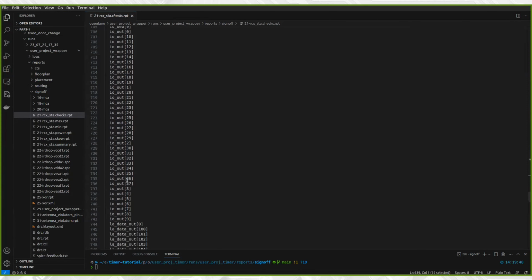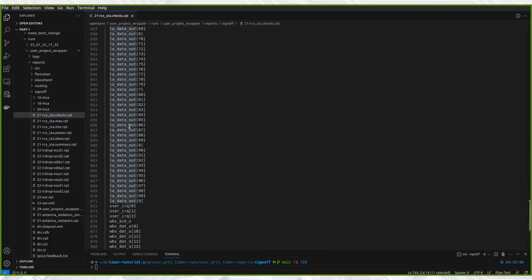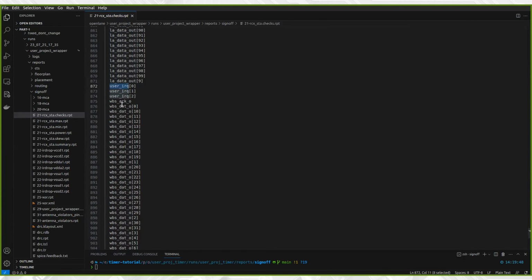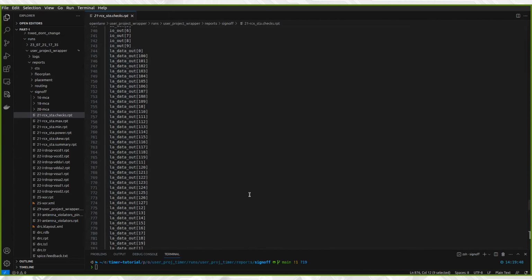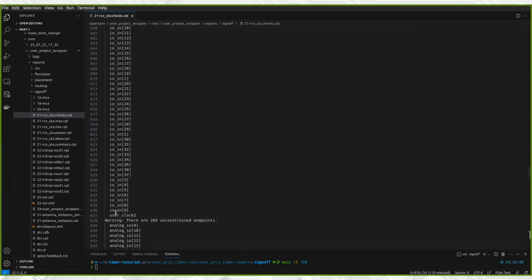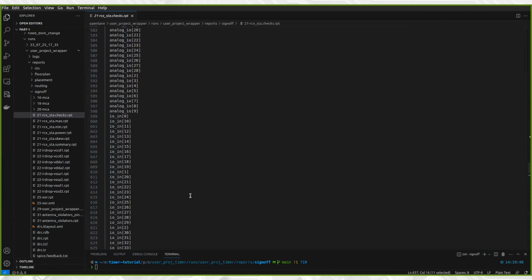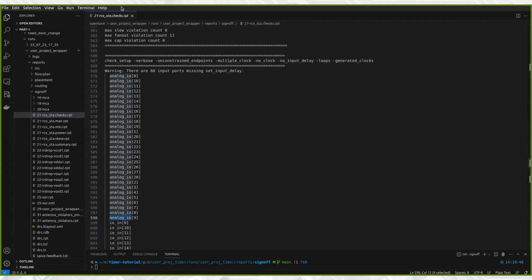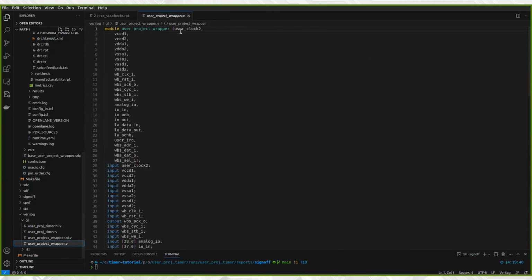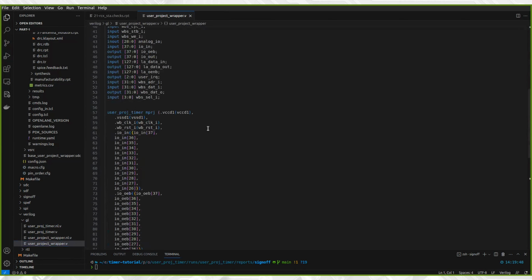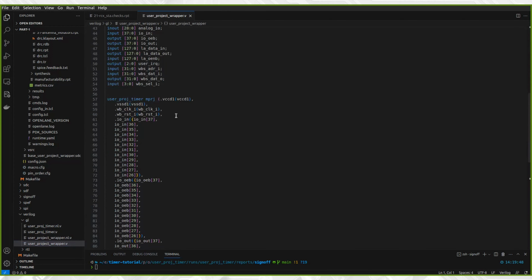Then go to the star-mca/rcx_star_sta.checks.rpt files and review the report_parasitic_annotation section for reported unannotated nets. The reported nets include the identified nets from the timer macro, as well as unused nets of the user project wrapper. Therefore, no new issues are identified.